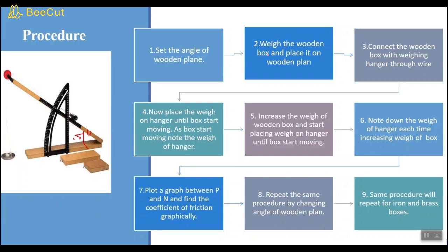I will weigh the wooden box and place it on the wooden plane. Then I will connect the wooden box with this hanger with the help of a wire. Then I will place weight on the hanger until the box starts moving on this plane.